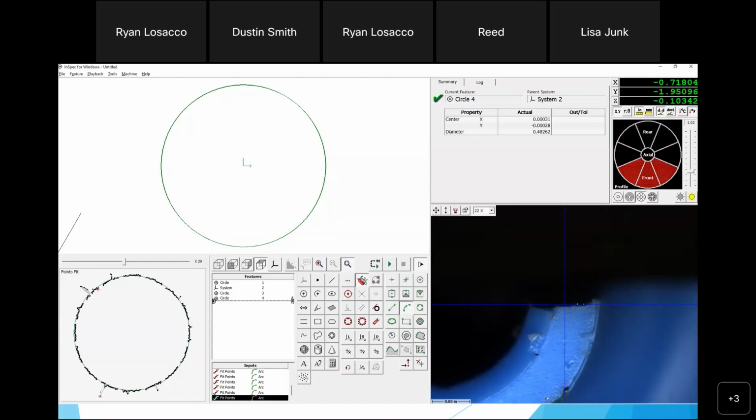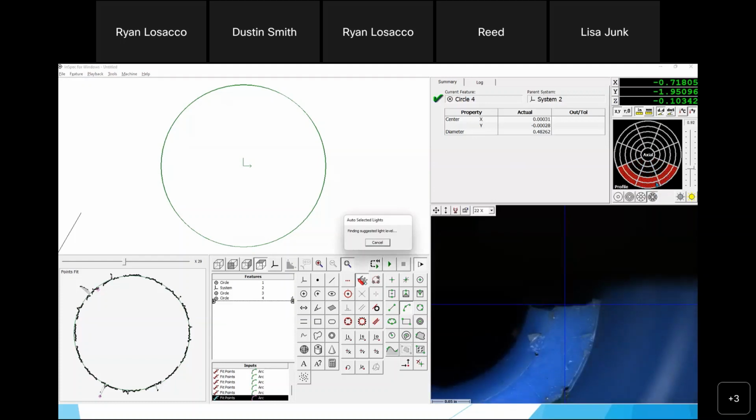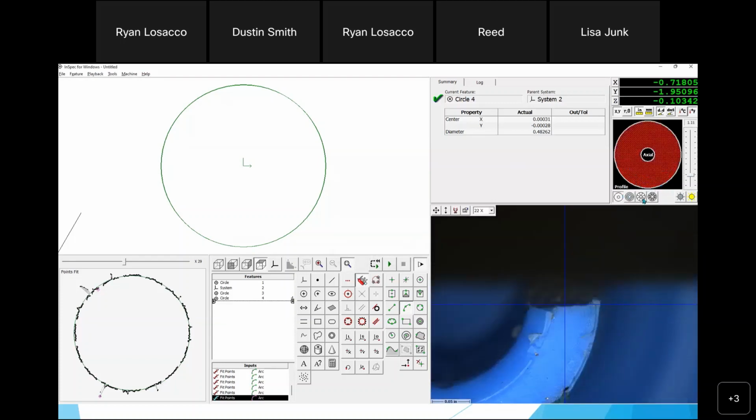Yeah, this is a section part, so I actually wouldn't be measuring this. But if this was still too much light, then I go down to segments and click and drag around my outer ring lights, just coming from this direction, to measure that feature. So I start here. If this is good, awesome. If not, I start subtracting lights.